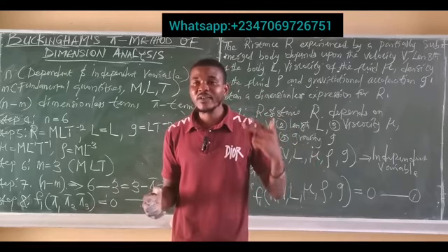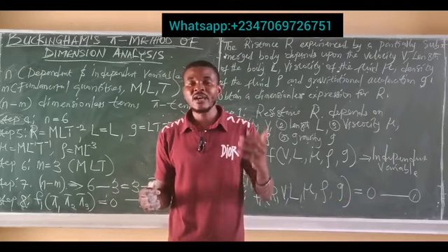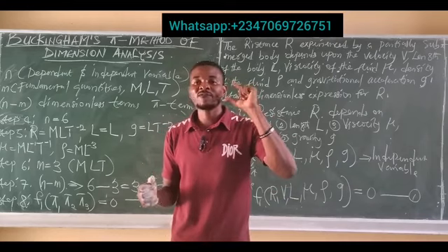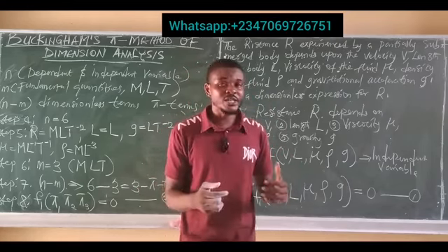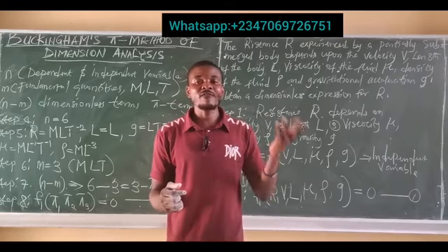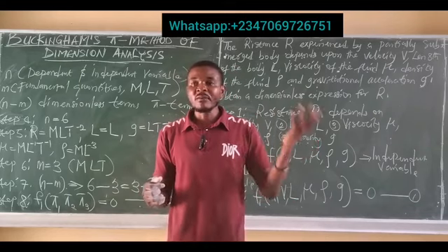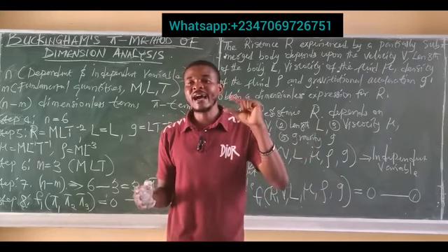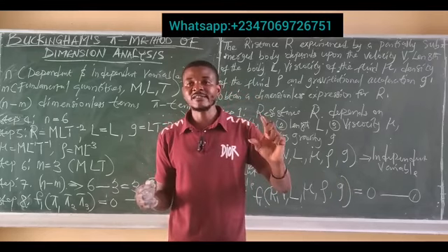Secondly, for the flow property, if I have velocity, if I have acceleration in a given equation, always prefer velocity ahead of acceleration. And lastly, for the fluid property, if I have viscosity, if I have density, maybe dynamic viscosity and kinematic viscosity, always prefer density above every other fluid property. Always prefer density.